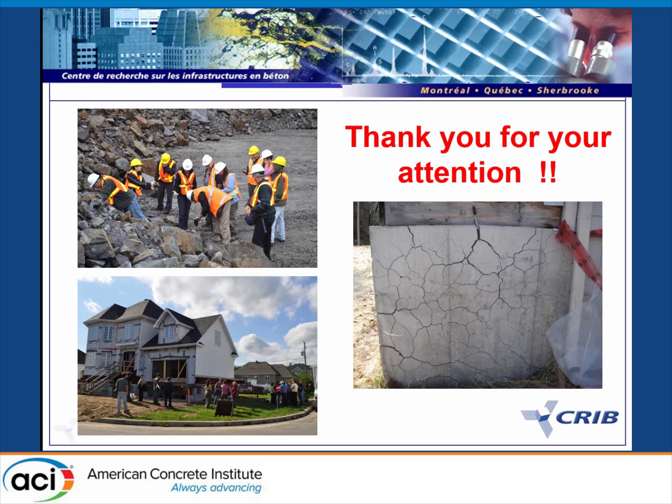Yeah, but it's in the whitish material around the aggregate particle most of the time. So it seems like this is a very localized problem. Like here in Quebec we have a problem, and in Connecticut we have a situation. So it seems more like an ACR type case where you identify the quarries which are the problem quarries and avoid them. So should the protocol be something like ACR's protocol?